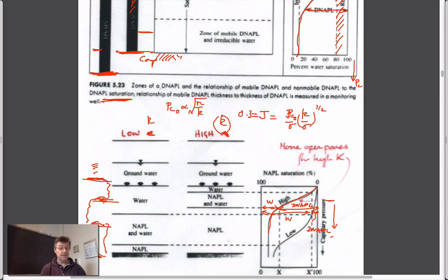And then ultimately, the place that can go no further is this really big capillary barrier that sits on the bottom. And so the kind of behavior we have is due to multiple capillary barriers that exist. And really, if you understand what happens at one of these, which is really what we're talking about here, then you understand all the components. So not an easy topic, but one that's, I think, important to what we deal with. So that's the first part in multi-phase flow.